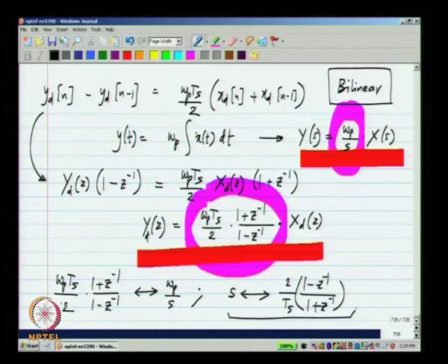Okay. This is the transformation from continuous time to discrete time. So, any transfer function described in terms of s, you can now describe it in terms of z and then implement it. Okay. So, we will quickly look at this for an integrator itself and for a second order filter.